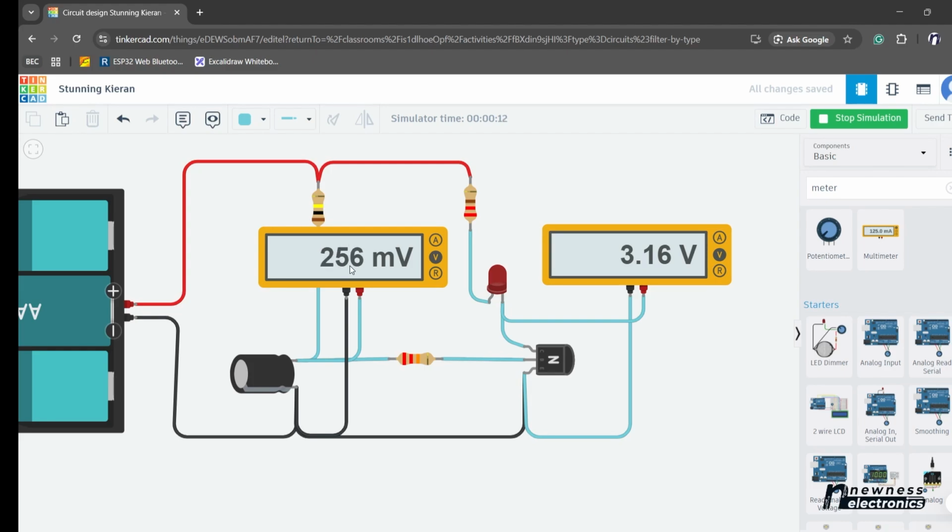See, the voltage is rising gradually. So this is to depict that this capacitor is charging up internally. It's charging up until the voltage begins to cross the 600 millivolts or 0.7 volt barrier. That's when this transistor, you see the transistor voltage is also reducing now. It's coming down. At around 700, it's on. The transistor is already on, but it's not fully on. Do you see what is happening internally in the transistor now?